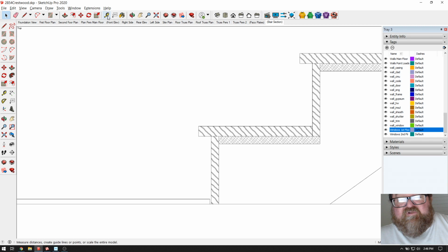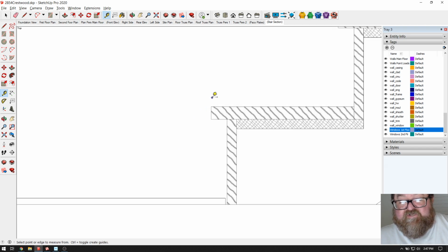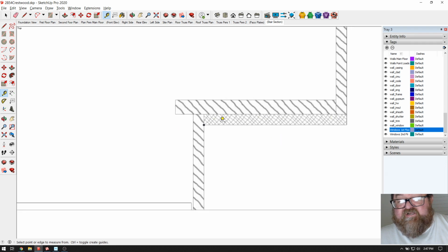Because the next important thing is getting this stringer height, this riser height of the first riser correct. Because you can see here, if we measure our finished riser is in fact 7 3/16. But guess what? We have to allow for our finished floor thickness, and we have to allow for our Advantech, which I use on all my stairs as a subfloor for my stairs. Yes, not many carpenters do that, but I do it.